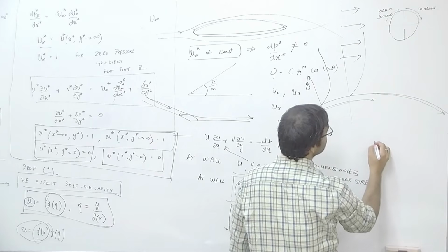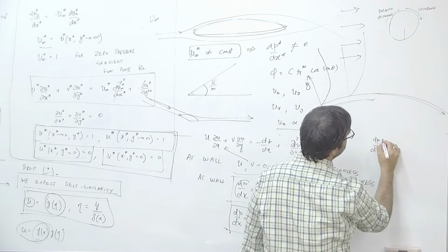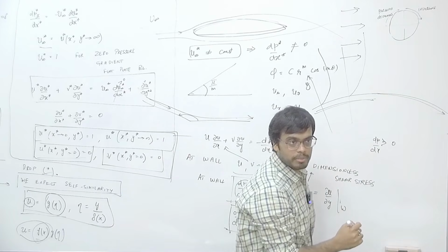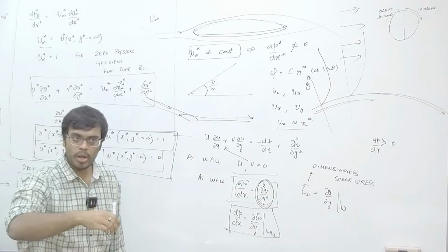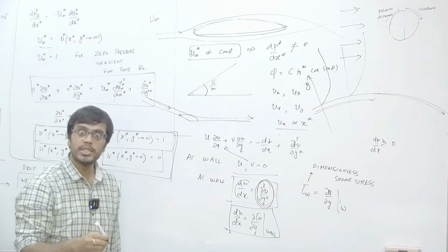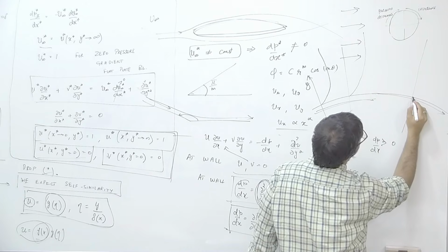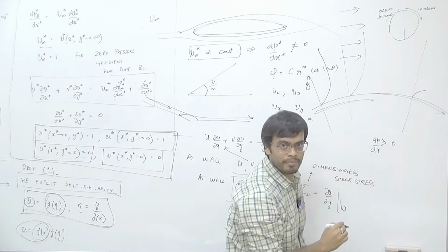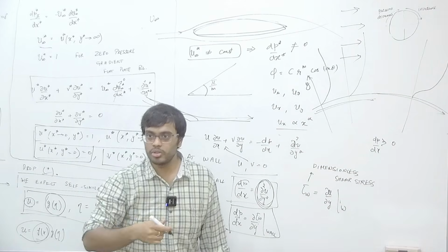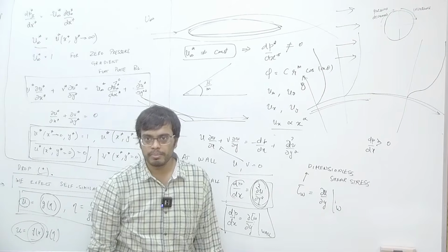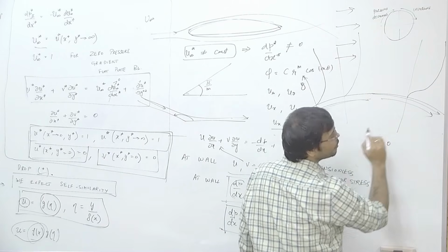Now, let us say we reach a position where pressure is increasing. So, dp by dx is actually greater than 0. What happens to dp by dx greater than 0? Del 2 u by del y square is greater than 0. So, at the wall the derivative is actually first increasing. At the wall you will see the normal derivative of velocity will first increase, okay, and then it will start to decrease because eventually it has to go to free stream velocity which is constant.